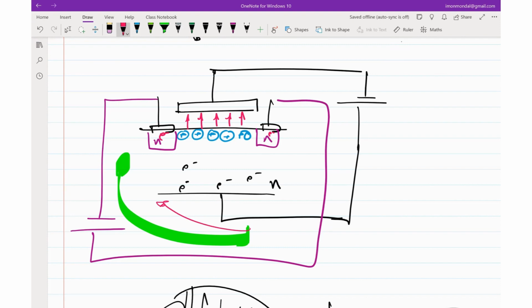Yeah, it looks like I can do that by increasing this vertical electric field so that the entire piece of this vertical dimension gets filled with only positive charges, right? But that is not a very trivial thing to do because these wafers are not that thin, right? So the amount of voltage that you will require will be quite high, and that is another thing that comes into the picture why you cannot do this.